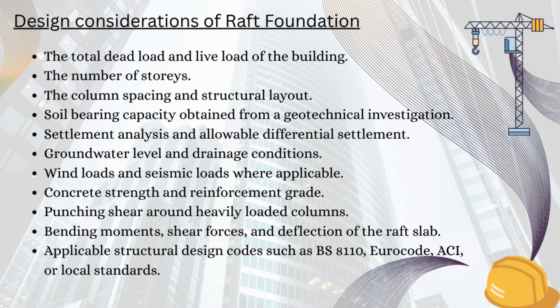settlement, groundwater level and drainage conditions, wind loads and seismic loads where applicable, concrete strength and reinforcement grade, punching shear around heavily loaded columns, bending moments, shear forces, and deflection of the raft slab, applicable structural design codes such as BS 8110, Eurocode, ACI, or local standards. These factors determine the raft thickness, beam sizes, reinforcement arrangement, concrete grade, and the overall foundation dimensions.